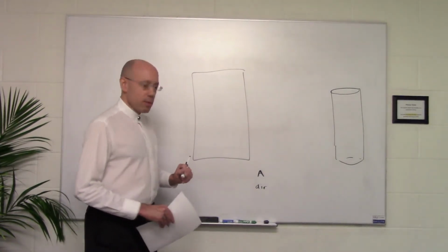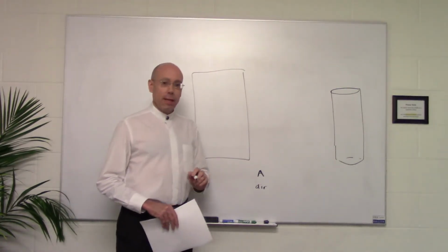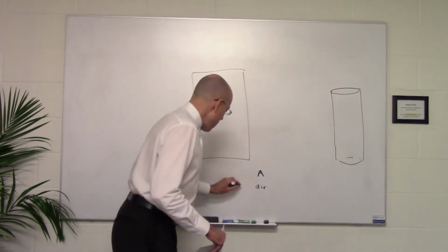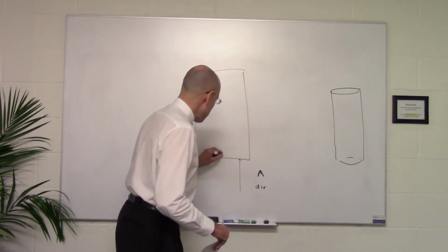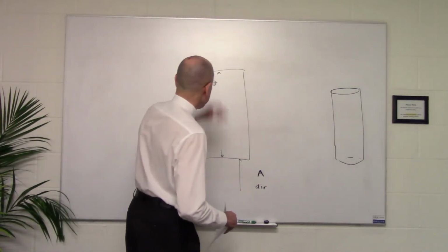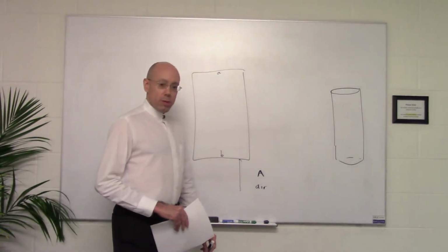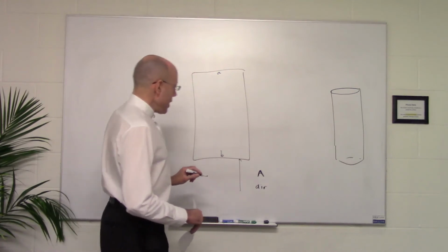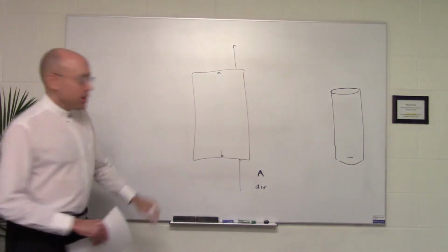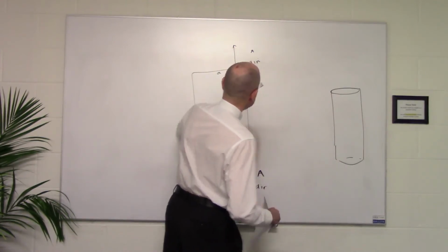The purpose of gas absorption or gas scrubbing is to clean up a gas, very often air, which has something in it that we wouldn't like to breathe or that's toxic for whatever reason. So we pump it into the bottom of the tower. I'm just going to call the bottom end of the tower B, but B doesn't stand for the first letter of bottom, because I'm just going to call the top of the tower A, and there's no commonality of letter there. So, what's supposed to happen here? Well, I'd like to get rid of the A in the air so that when the air flows out the top of the tower, there's much less. So I'm going to say the air here, and I'm going to put a tiny little a here, because ideally that will be a very small amount.